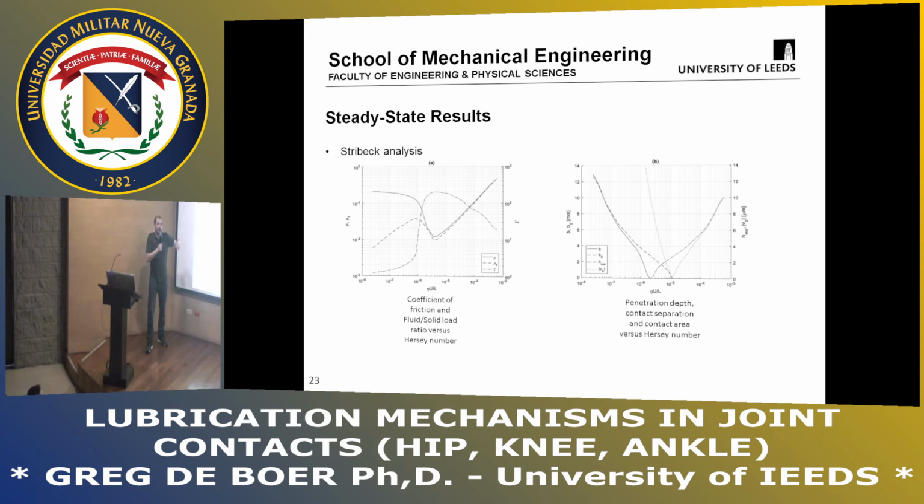You get high friction where you've got lots of solid on solid contact, and where you only have a fluid film, you have lowest friction. And this is the same location as here. So here, the bodies start to touch, and after that point, your friction increases. So again, this is giving us some insights into what the friction behavior in a poroelastic type problem looks like.